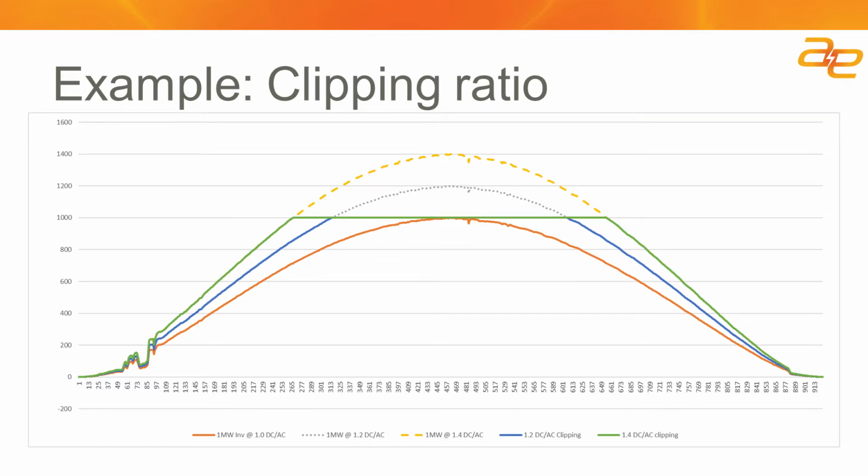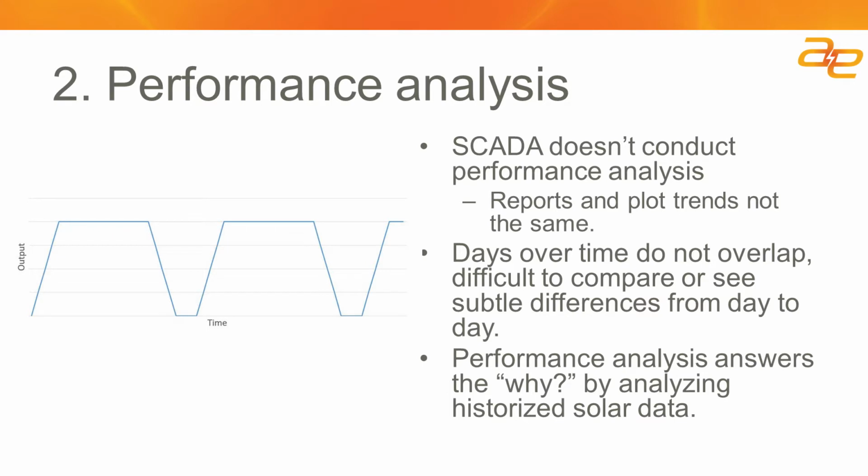So you can do the math on a clear sky day to figure out what the effective DC-AC ratio of any inverter is, and that might be information that you can use to say things are running well or things aren't running well. That's probably the hardest normalization routine I've had to do at a site before, but I think it's also pretty valuable. Performance analysis and analytics, this is a challenging area because the easy temptation is to say,